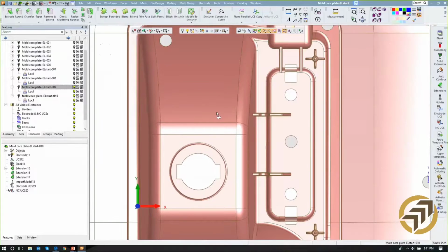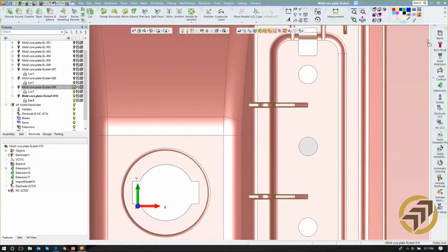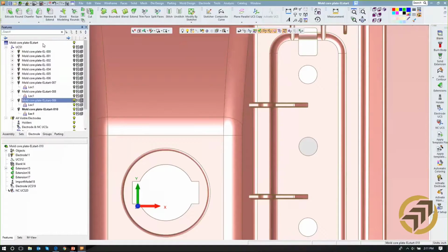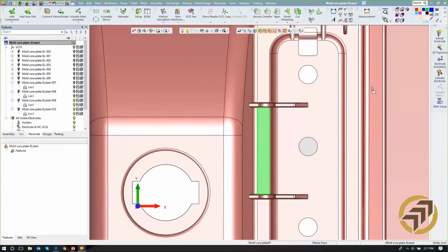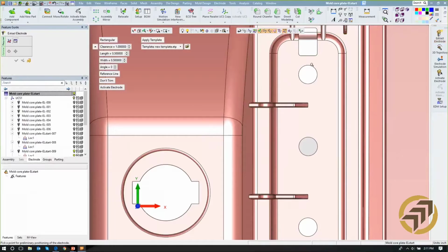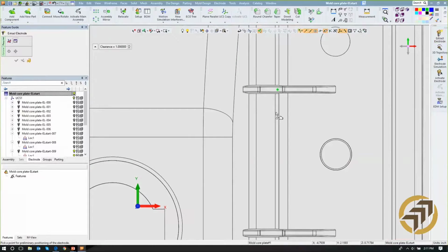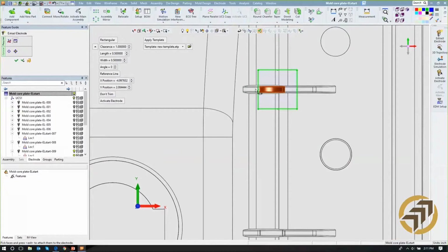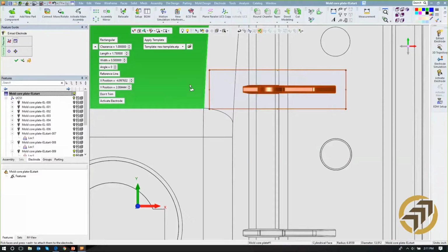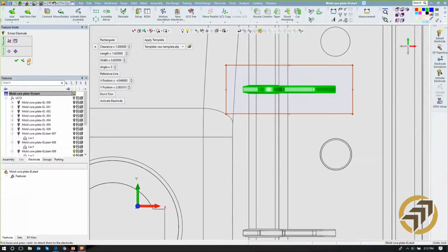Also, there's another set of tools that we can work with that's very, very handy. Pull an electrode using this long rib area here. All right, so again, we'll extract it, focus in, say in this area. Again, this is like a rubber band. It's going to snap to standard sizes, of course, which I can control. That's the feature I want. So again, fit it, center it, all that is done.